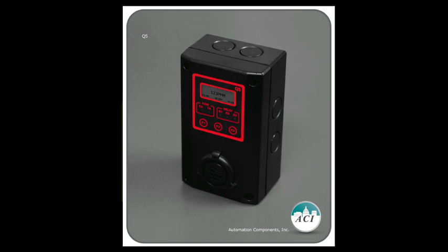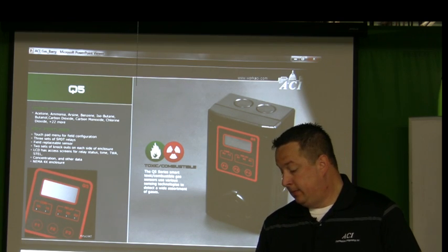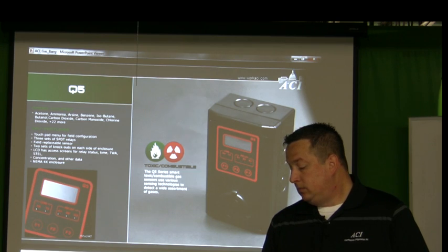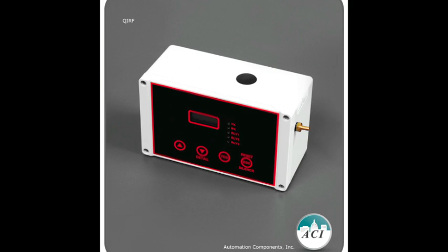On the display, it has a receiving and transmitting LED, and it also has an LED for each of the 3 relays, so you know when you have a visual alarm of that being tripped. It also has an audio alarm. I believe it's 80 or 90 decibels. And all the setups are driven through the front menu keypad, and that has a display so you can go in and set any of your relays, any type of ppm level.